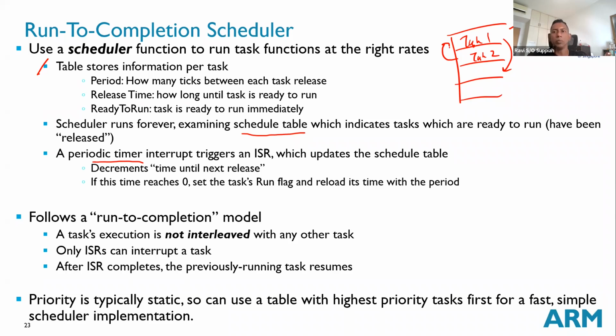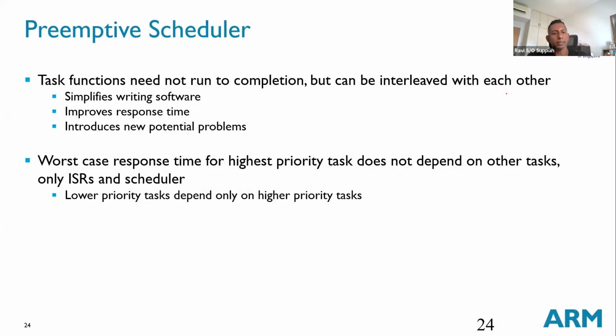The only thing we need to think about is what tasks we want in our system, how they will communicate with each other, and how they will synchronize data. The lower level implementation of the scheduling and the policy behind it is managed by the OS very nicely. That is the good part of integrating an OS.